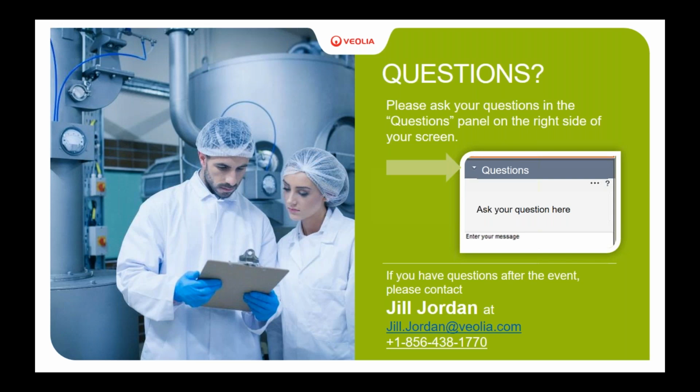So if you're planning to have an equalization vessel that is timed at 12 hours, you probably want to collect composite samples over a 12-hour period. But the basic idea here is, if you're just starting to make a decision, implementing a good testing program consisting of not just composite but also grab samples is what we usually look for.